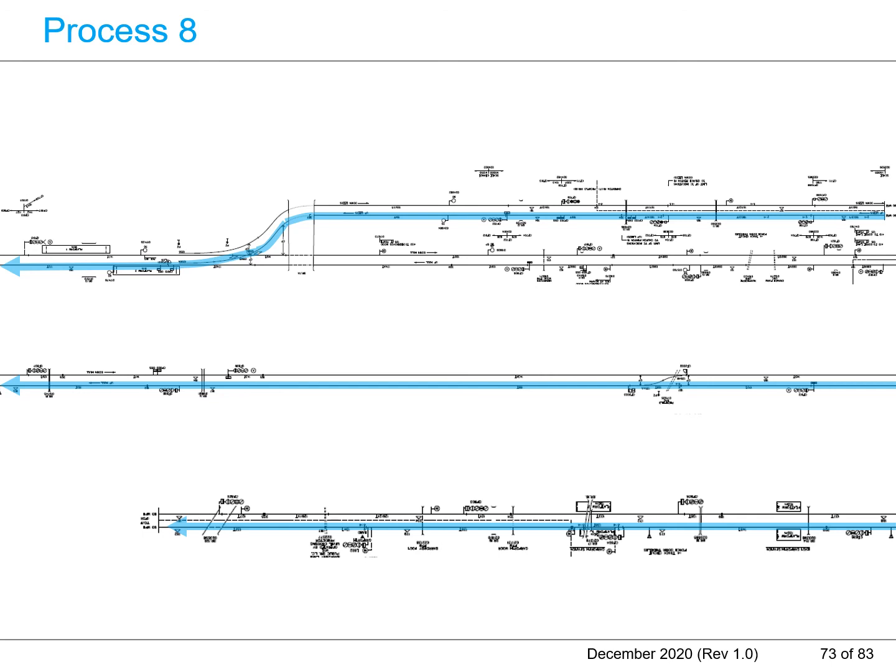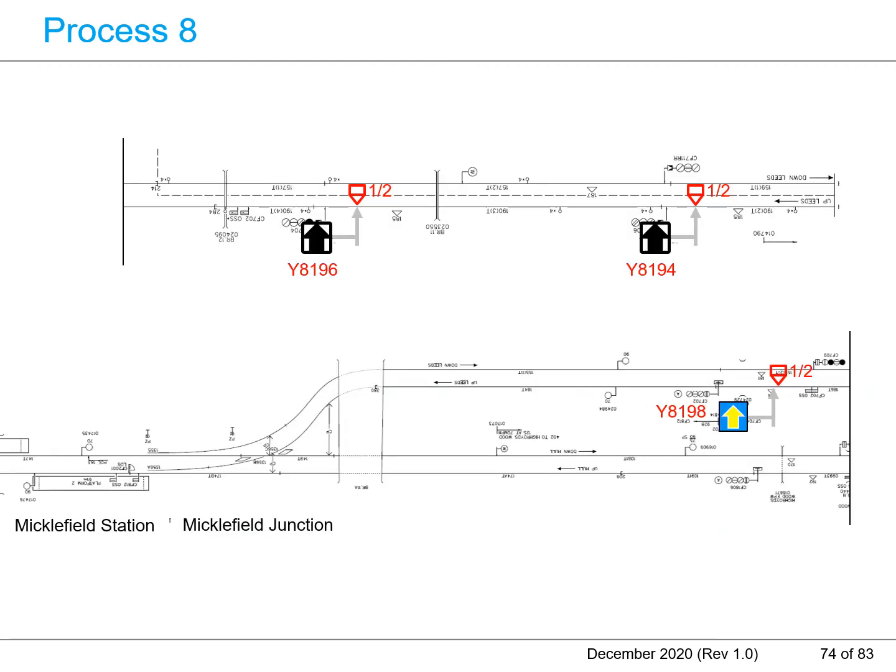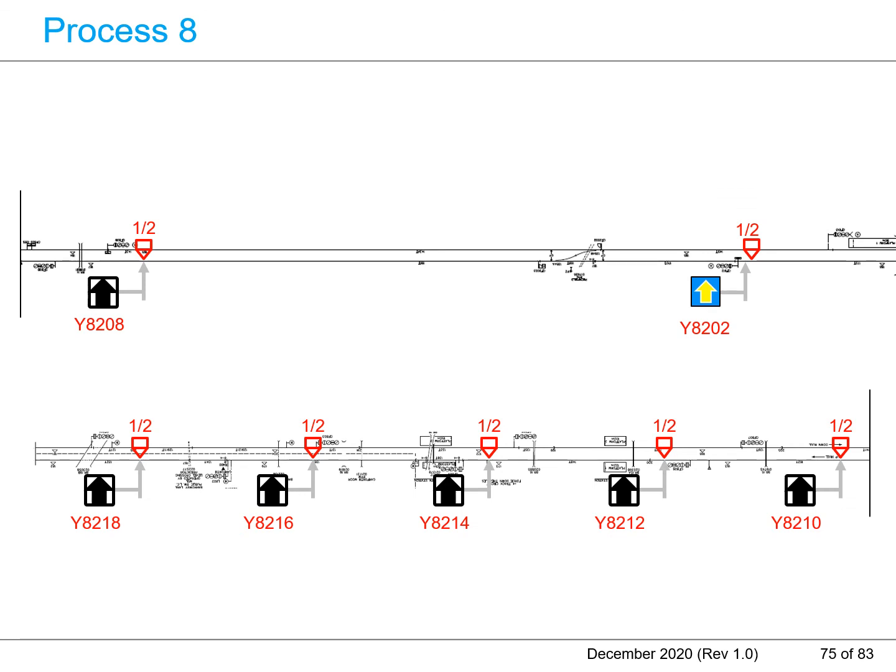The ETCS operational direction for the other unidirectional line is still the nominal direction. There is no direct relationship between the ETCS nominal or reverse direction and the up or down naming convention. This diagram shows the RSP and the EOA balise groups on the approach side of the Micklefield junction. This diagram shows the remaining locations of the RSP and the EOA balise group beyond the Micklefield junction.